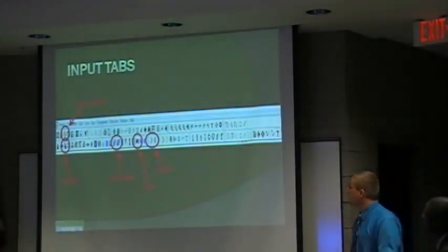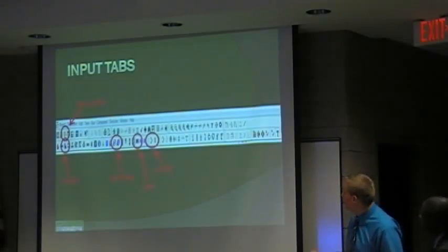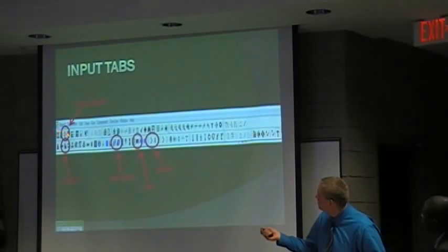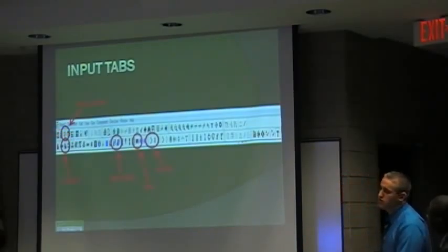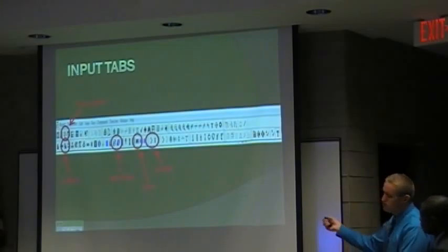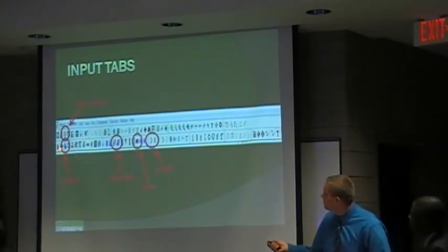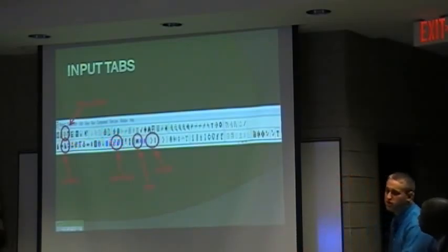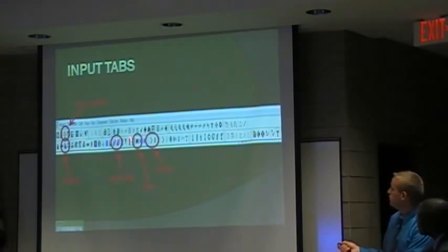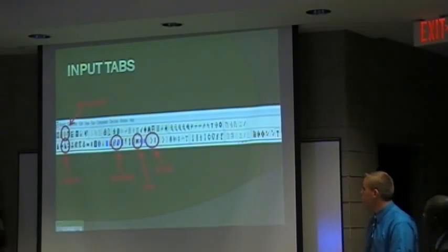These are some input tabs that Power Tools for Windows has to offer that we can insert, make our one-line diagram, and run analysis on. Up top here is our TCC curve. We can run all of our TCC curves and breakers, and I'll show you that in a minute. We have our little cable diagram. These two here are our induction and synchronous motors. We have our UPS system, and then our two breakers, or current protection devices, and fuses and circuit breakers for those.